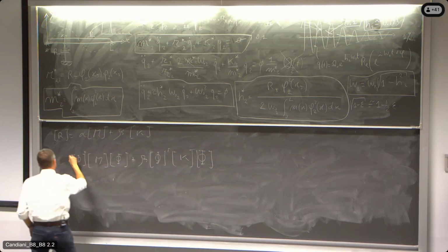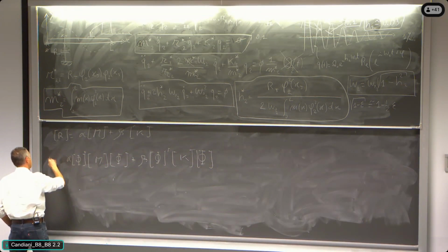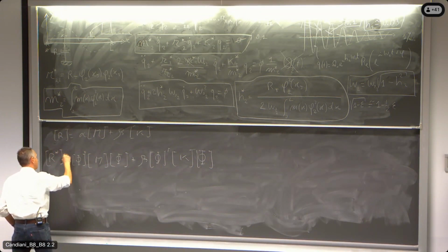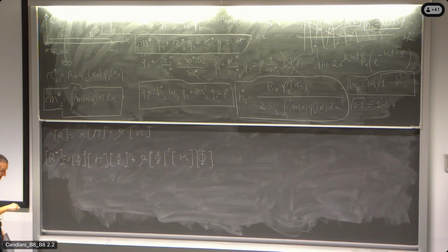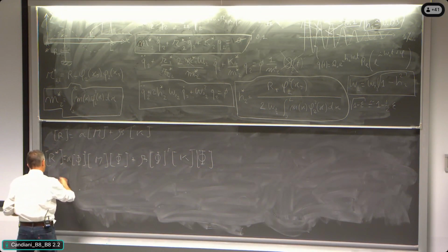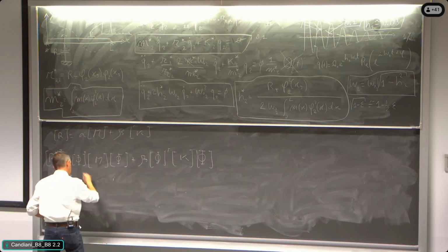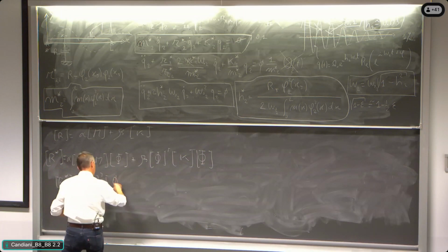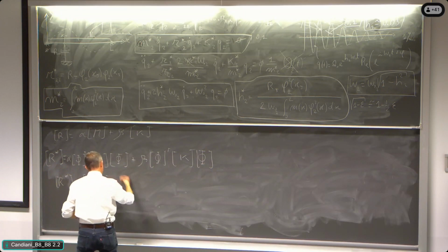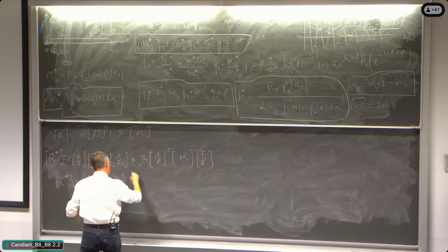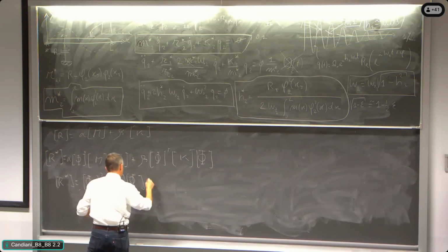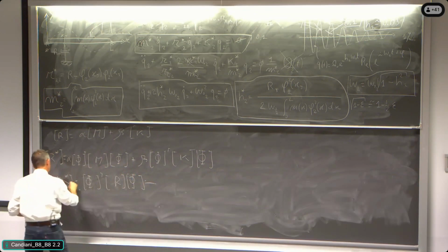All right, and this is alpha, and so this becomes R star. So if we are translating everything into principal coordinates, it happens that the matrix R star, equal to phi transposed R phi, becomes diagonal, is diagonal, all right?